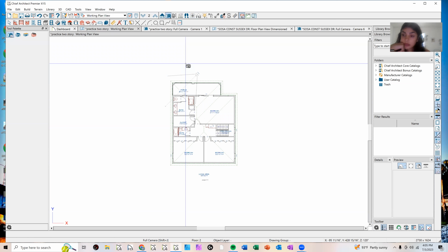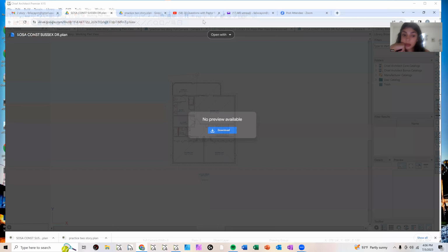But sometimes we have to make what's called a stem wall, which is we're making a footer all the way around that's higher. The way we build this house is we build a wall all the way around the house on the bottom. It's just like feet. It's not actually the house, it's just feet. And then inside of that, we pour dirt. So it's like a container for the dirt, and then we pour the slab over the top. Let me see if maybe I can show you.